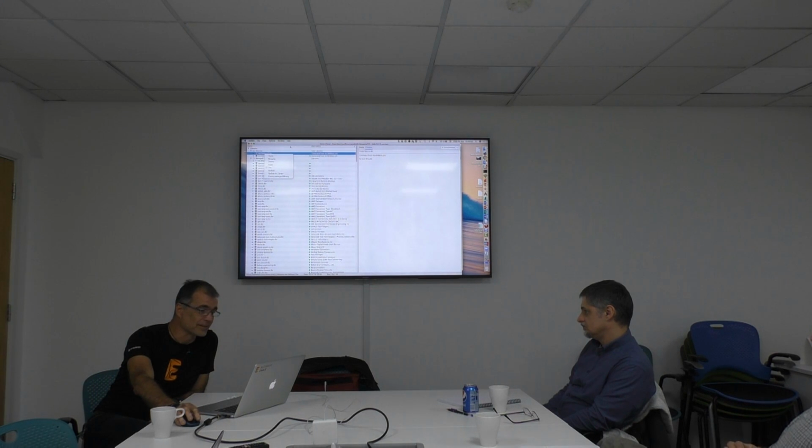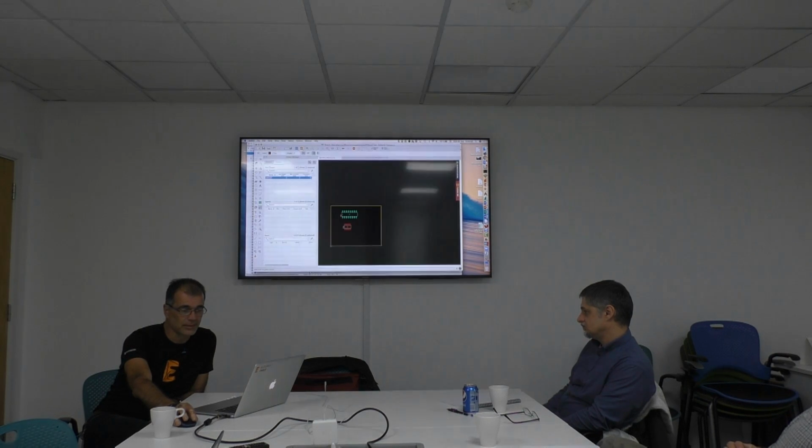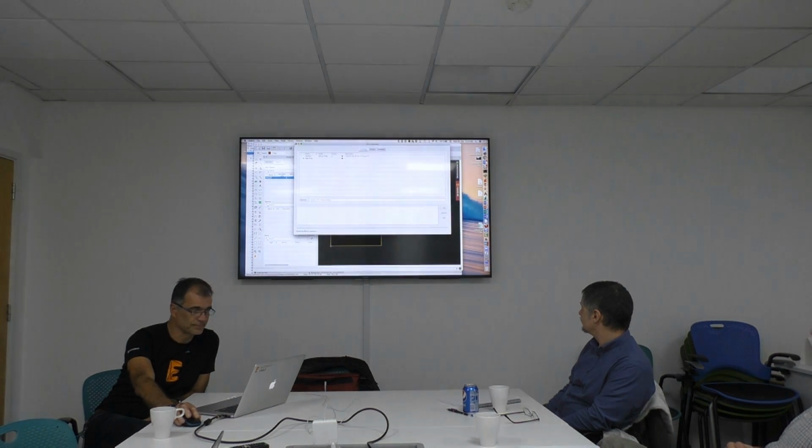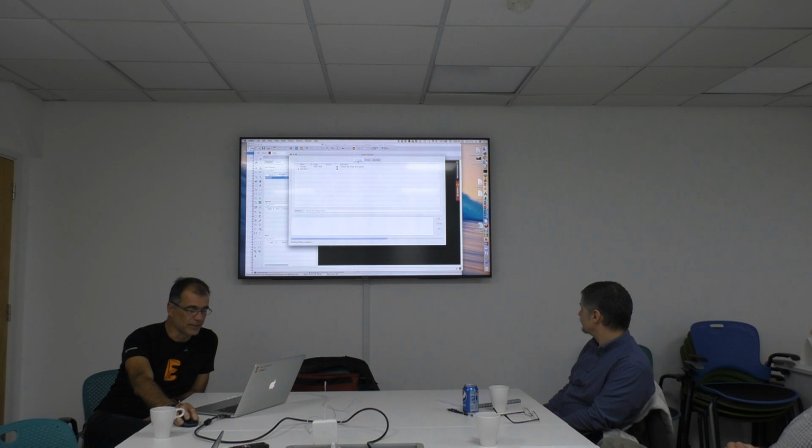And perhaps before, about the library updates we have. If I'm in the board or in the schematic editor, I have the library menu, and there I have the library manager. If I open this one, I have a list. Here you see the tab In Design. Eagle tells me I have components from these two libraries in my design.